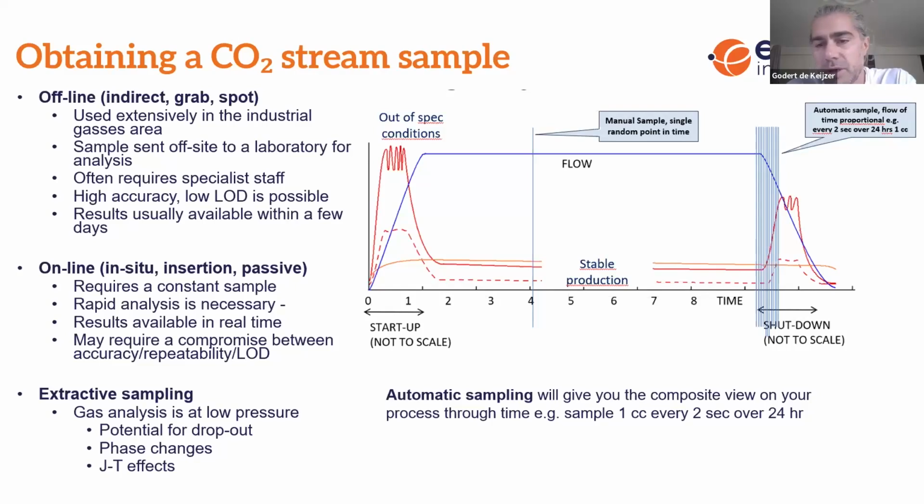And those you also want to measure to make sure that as an aggregate, you remain within the impurity levels that you should be. So what you can do through an offline sample is you basically catch the samples under the conditions that they are in the pipeline, and that's very important because, as we'll see later, conditions of bringing it back to